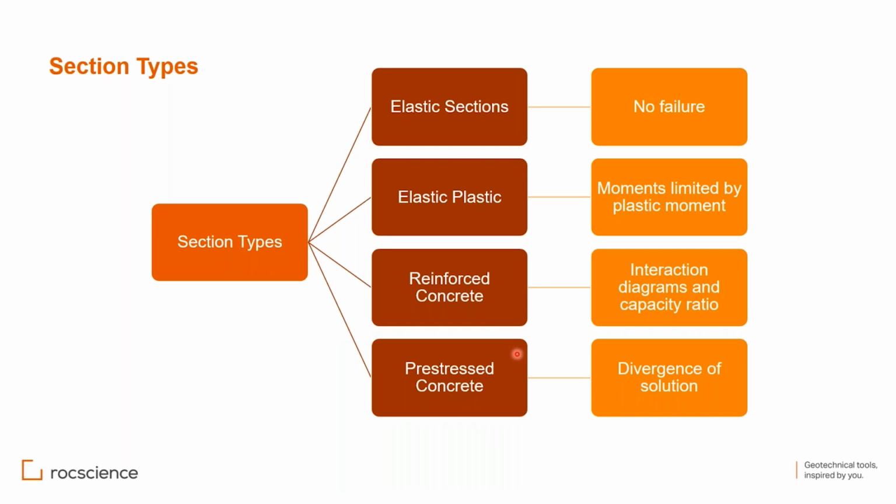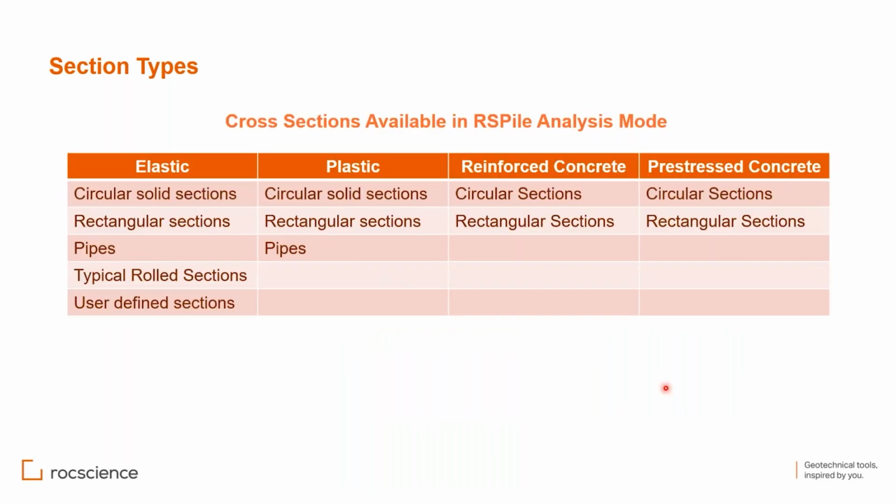unacceptable code-wise. But even though it may be outside the unfactored surface, for the pre-stressed concrete, the only way for now in RSPile to know that your section is not adequate is that you have a divergence in the solution. Your pile will not be adequate to hold the loads you have applied.